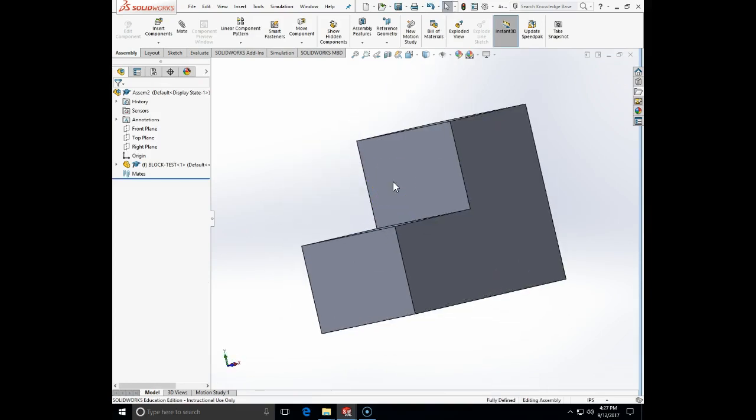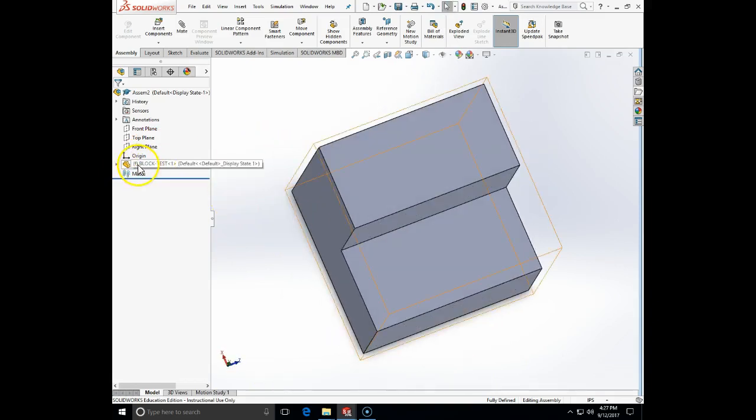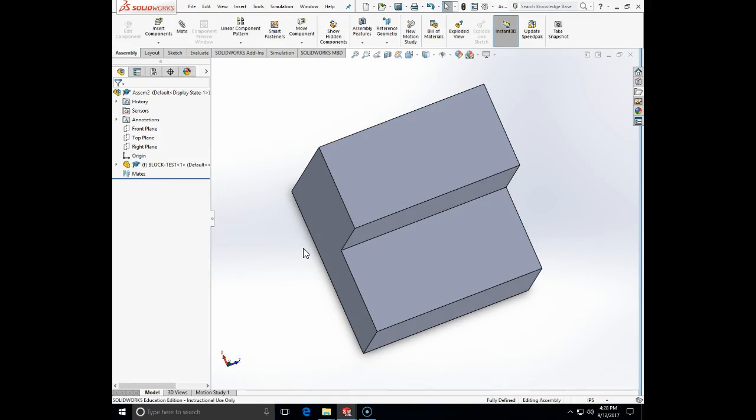And we brought that part now into the assembly view. In the assembly workbench, you can see here on the parametric tree we have individual parts, and then we have mates. Mates will define how individual parts are arranged in space relative to each other. The first part that you drop in will by default have an F prefix, which means that the part is fixed. You see, we cannot move it. If we want to be able to move it around, we will right click on the part and click on float.